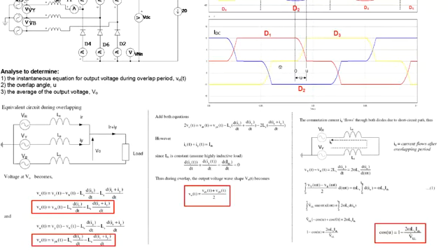You must understand how you get this 0. You actually refer to that particular current. So the lower limit is 0, the upper limit is IDC, because you start with 0 and you end up with IDC. So that is your integral from 0 to IDC of diu equals to omega Ls IDC. So you solve this, you get omega Ls IDC.